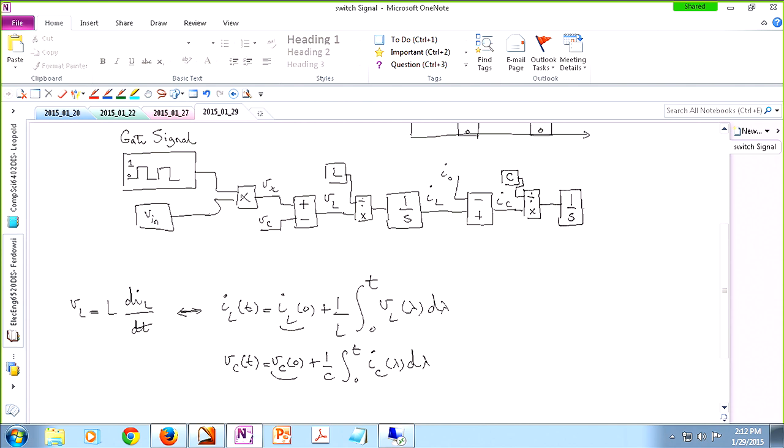And that would be the capacitor voltage or the output voltage. All right, now we have the output voltage. We needed the output voltage earlier, so I just close it over here. So this is one loop. And then we also need Iout. So looking at the topology, Iout is nothing but Vout divided by R.